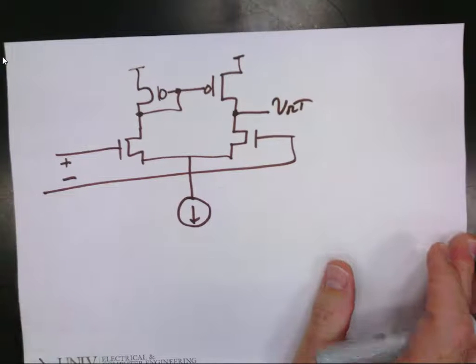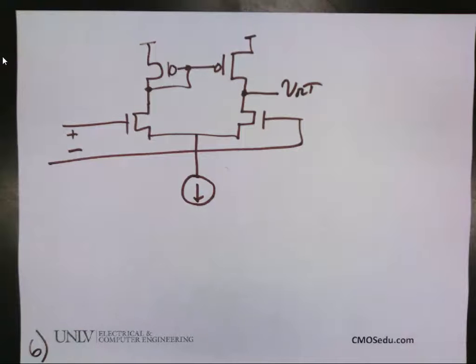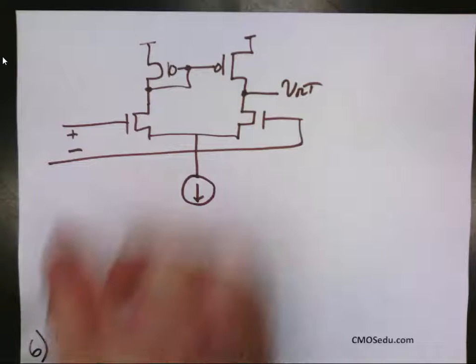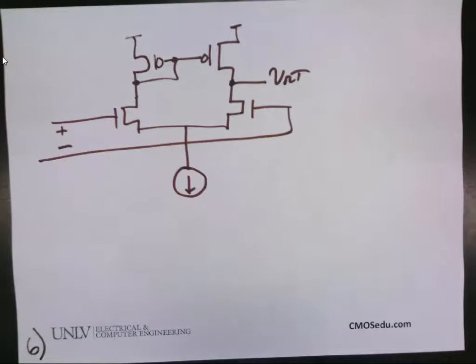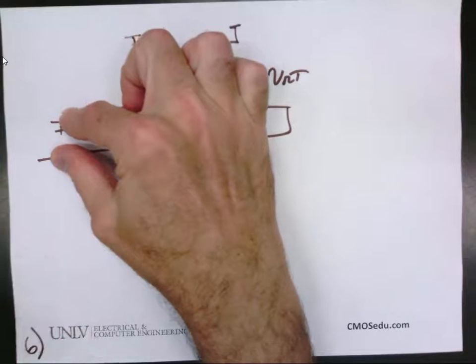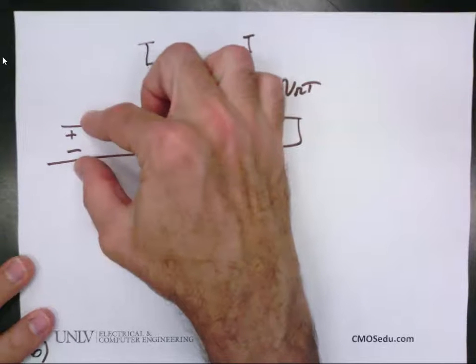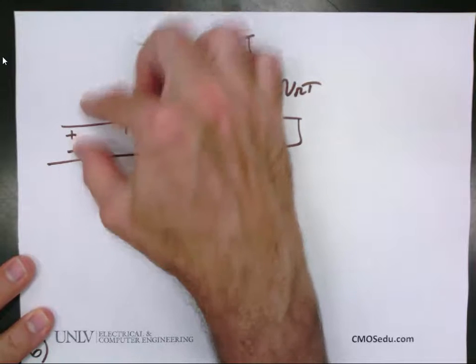Okay, so noise. When they design, like in your motherboard, your computer or your cell phone, whatever, they transmit the signals some distance. There's generally about, I used to know this better, like 100 picosecond propagation delay per centimeter on the printed circuit board. When you transmit the signals, it can pick up interference. So there could be something coupling into the two lines, the two wires here. The common mode, which we're going to use a lot, and it's used in industry a lot, is nothing more than the signal that's common to both wires.